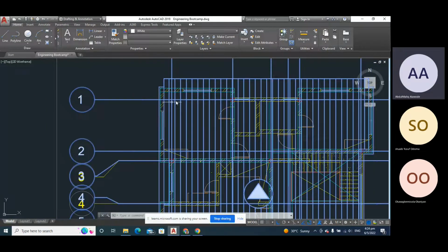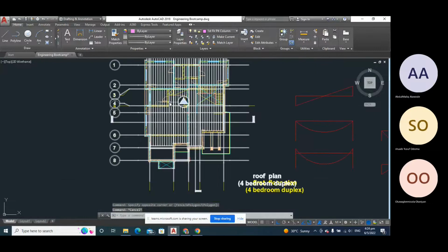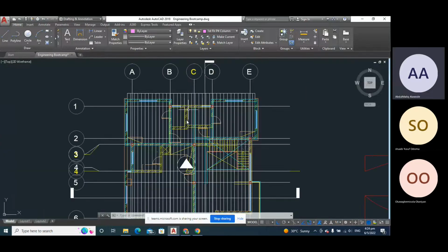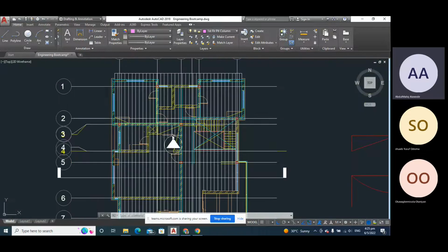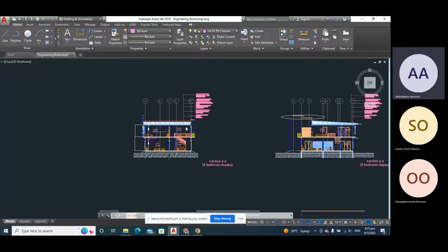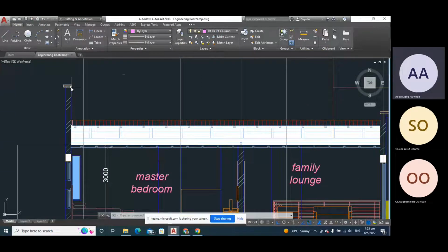And what we have gotten from our section is that this roof is one way. What I mean by one way is the draining system is to the back. From this arrow we are seeing, all the water is going to go to the back. It's just one direction. And we can see from our section that at the edges, the architect has designed the roof such that on the right, left, and front elevation, there are block walls there. So the roof is hidden.